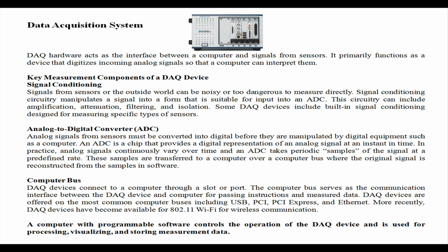You just made sure that they were all converted to some kind of a voltage. And very often those voltages are very weak, very small voltages. Most often we talk about millivolts. We often say that we excite the sensor with a certain voltage, and when I excite it with so many volts, maybe the full scale could be so many millivolts. That's the kind of interpretation we do. So the voltage signals, even full scale, are rather weak. So sometimes we may need to amplify them.